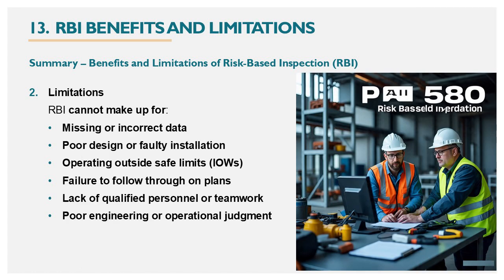Number 2 is RBI limitations. RBI cannot make up for missing or incorrect data, poor design or faulty installation, operating outside safe limits or integrity operating windows, failure to follow through on plans, lack of qualified personnel or teamwork, and poor engineering or operational judgment.